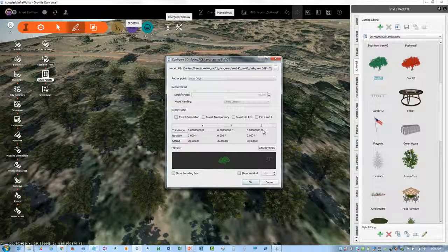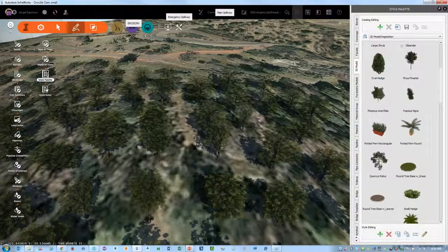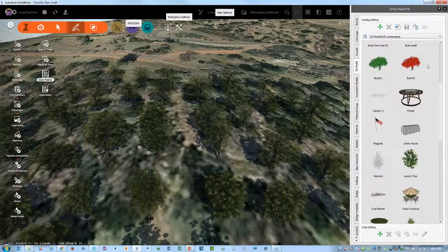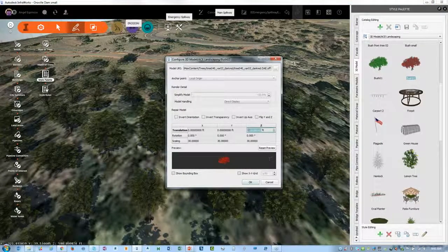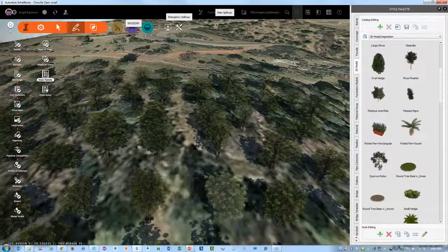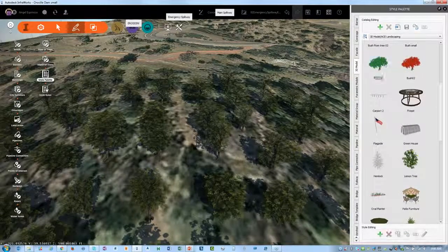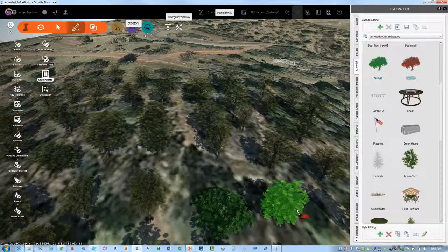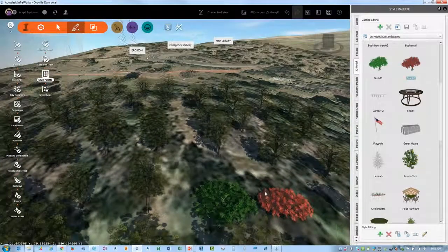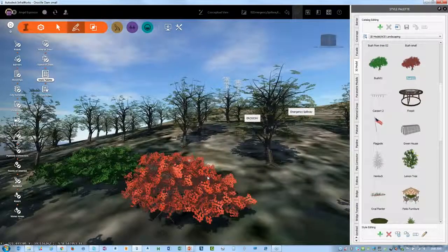and modify it, distort it. So I'm going to say, well, what if the tree was actually, instead of dropped in at its foundation or its base, 0, 0, and whatever roots typically that are underground, I'm going to say, let's push this down about 5 feet and hit OK. And I'm going to do similar to the other one. Landscaping, bush 02, the red one, push that down about 5 feet, hit OK. And then, as is possible and what we already saw, I can then just drag and drop these on here. And what we're seeing then is more something that's closer to the ground, right?